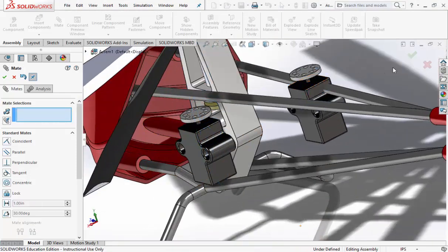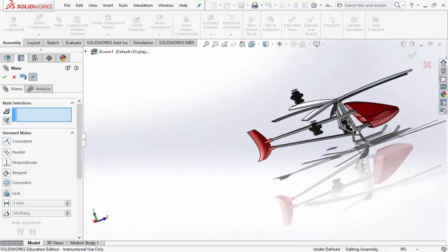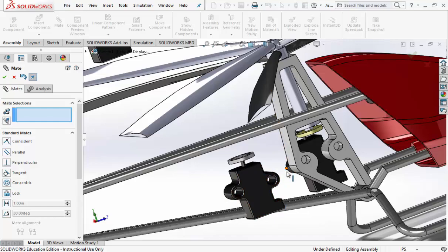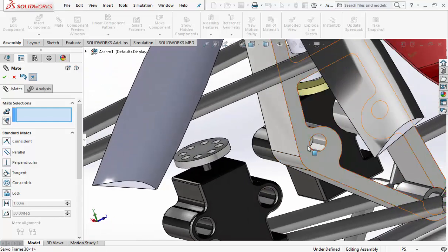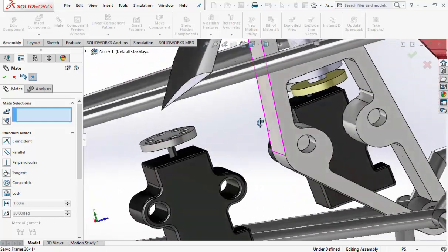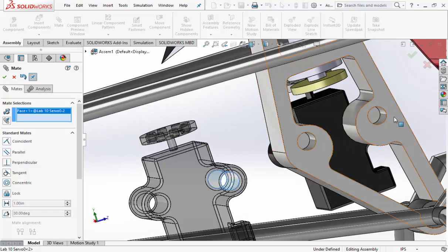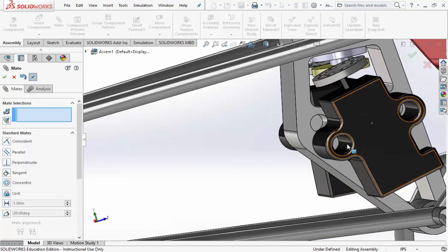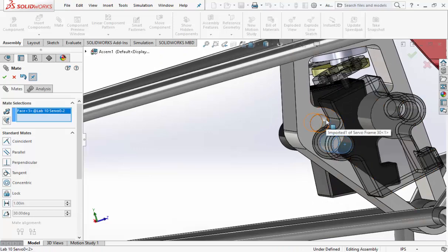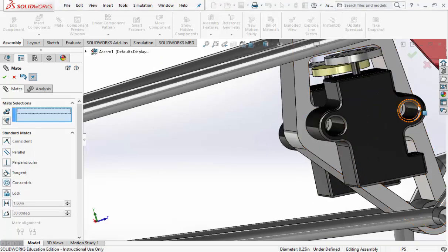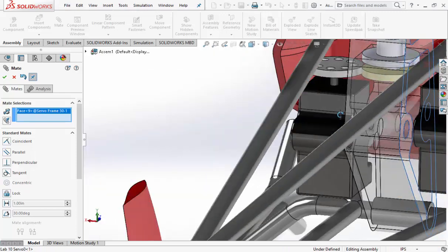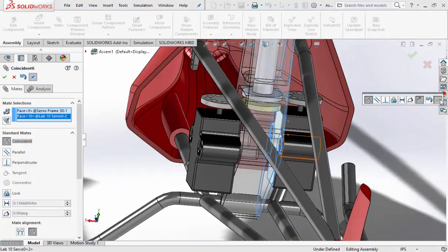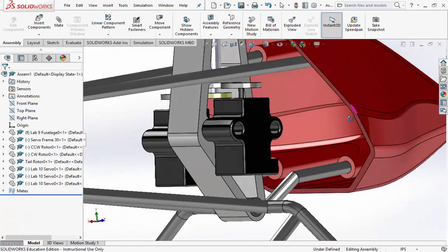The back one's a little bit trickier. I'm going to spin it around to the back. Notice that these holes are actually in a different location. They're actually a little bit above the other side, which is good. Alright, inside of the one to the inside of the other, check mark. Inside of the opposite side to the inside of the opposite side, check mark, and then face, spin it around to face. Check mark it twice to finish it.